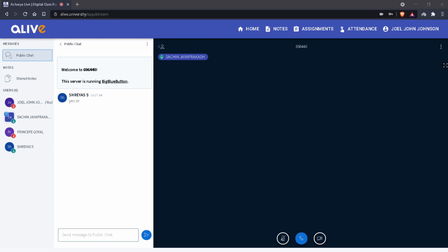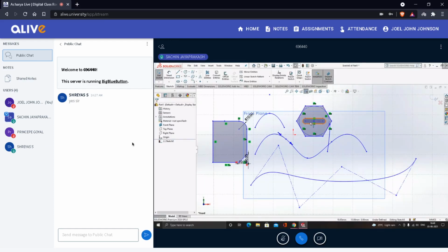Based on the selection of where you want the slot exactly, you can select one point. Similarly, select one more point, and you can select the size of the slot. Okay, so you can do this slot, and later when you extrude it, you will have a space in between like this, the slotted space.